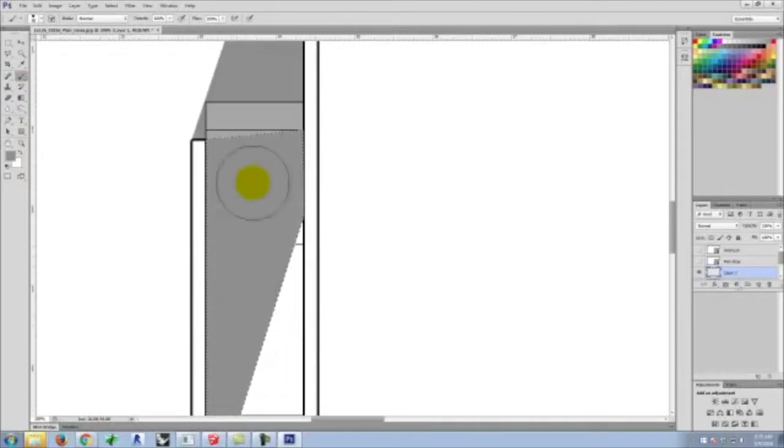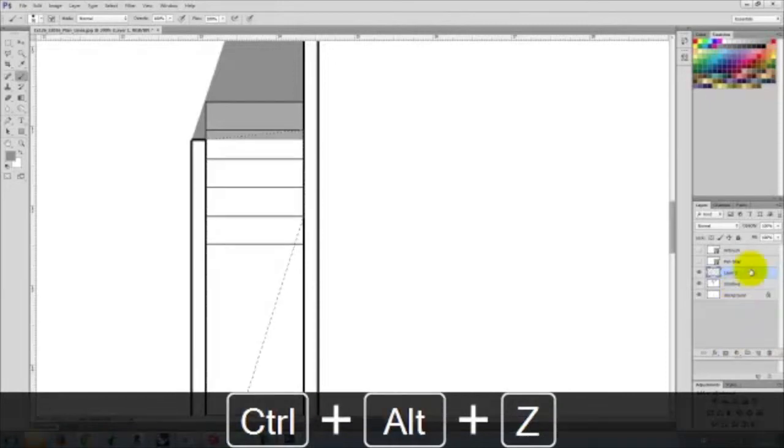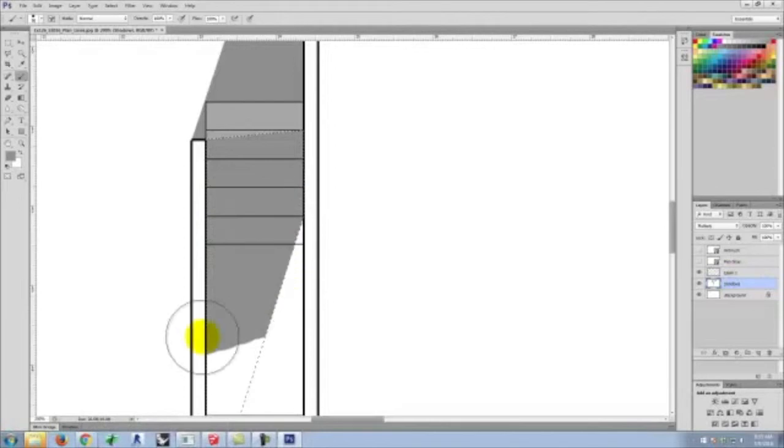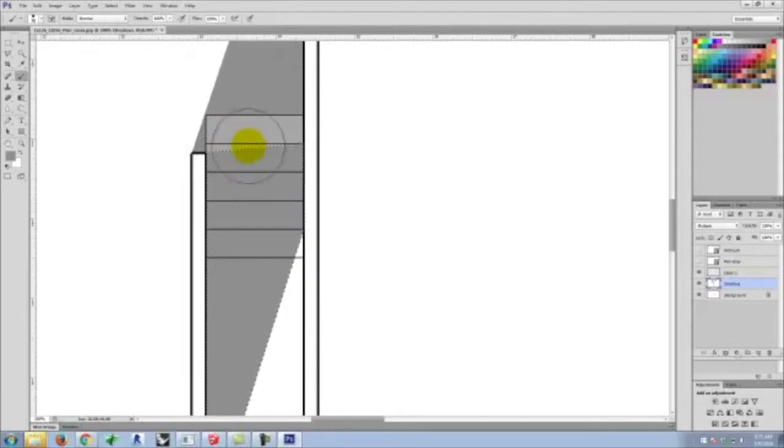Now, this went on top of that layer because I drew it on that new layer instead of the shadows layer. So let me back up one step or two steps. Let me change to the shadows layer, and then I can fill it in like this. All right? And it looks like it changed the color of those stairs. That's how SketchUp did the shadowing.